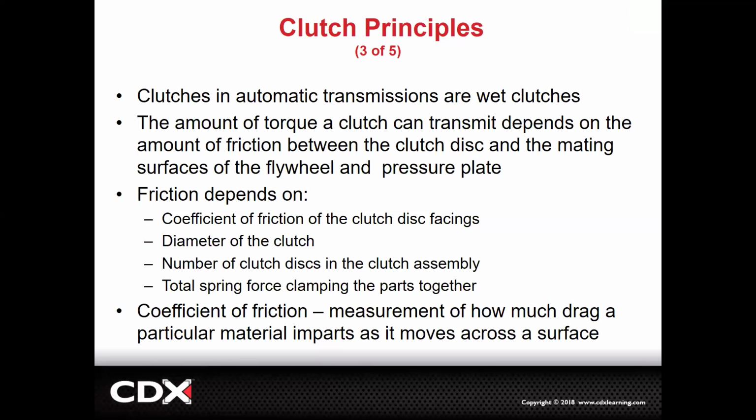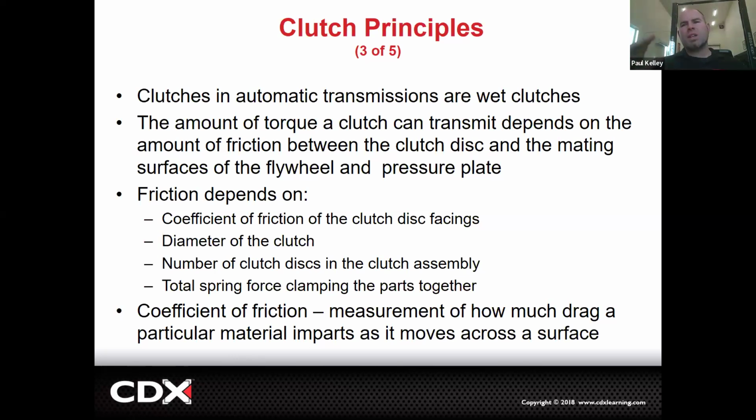Roberto, go ahead. You know about that, huh? Oh, I was going to ask, do those clutches wear out faster than regular ones? It depends. I'll give you an overview. The stiff spring will not cause it to wear out faster. But a lot of times with the stiffer spring, and they're trying to make more power, they'll go with maybe a different type of lining, like some carbon fiber or some different mix. That performance clutch may wear out faster, but the spring itself actually will not make it wear out faster.